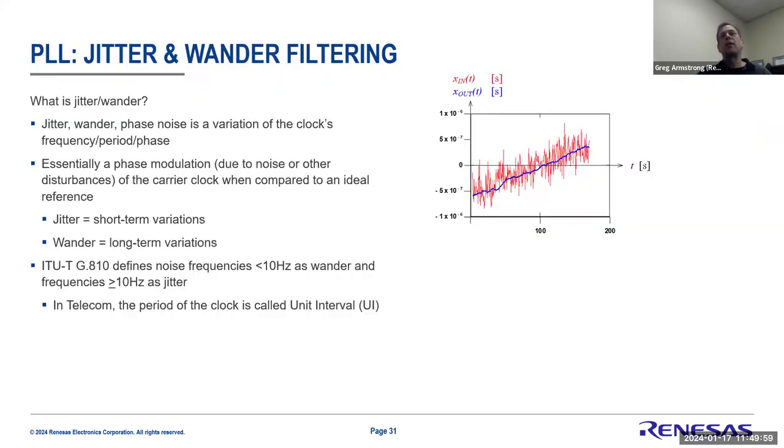So as a final component of the servo, let's look at the noise, because that's one aspect that a lot of times gets ignored. A lot of times people will tell you the performance of something and say, look, when I'm locked to the grandmaster and look at my error over time, my error is only off by 10 nanoseconds, right? But that's under a very ideal condition. But the reality is there is no ideal condition when you deploy this into a network.